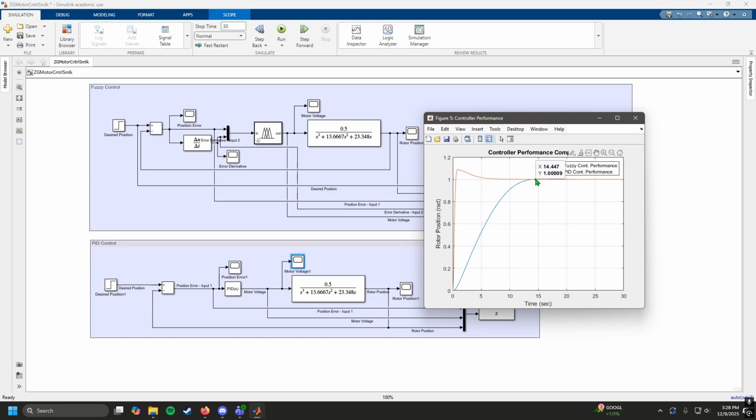Obviously, one isn't necessarily better than the other because you could design something like a chemical vat tank. If you design it to where it's got enough overhead that a little bit of overshoot isn't going to make any of the content spill out, and you desire to have your process running faster, then a PID controller could achieve what you're looking for.